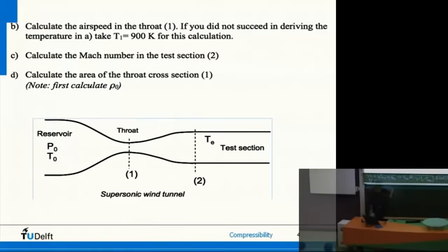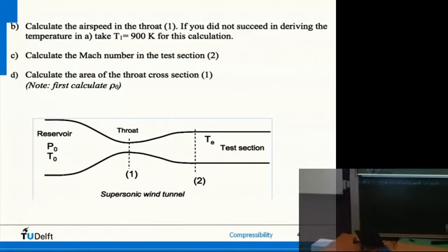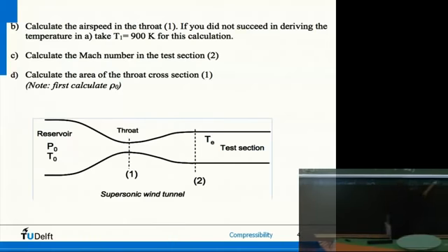So this is constant. And what is it equal to? It's equal to the mass flow. And you can check it, because we have rho, kilograms per meters to the third, area, meters squared, v, speed, meters per second. So what is the dimension of this? It's kilograms per second. So how many kilograms of air go through this area per second? So it's the mass flow.